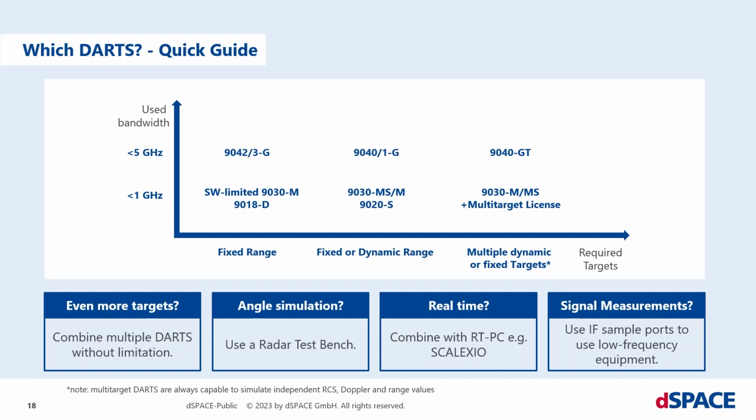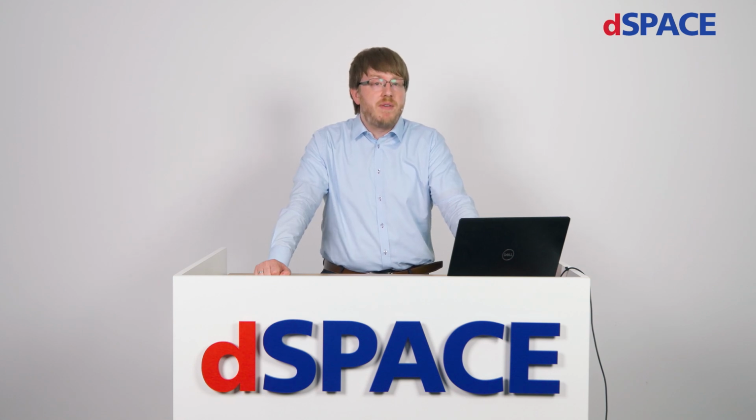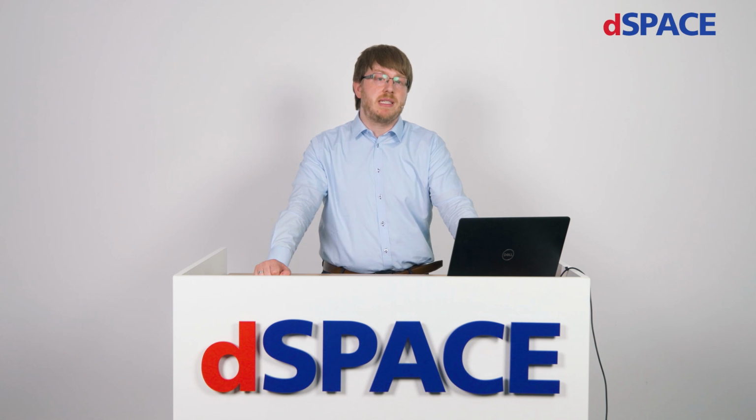As you saw before, these systems are very powerful and can be modularly expanded to include more radars, other sensors, or generally components that should be covered by a test. And the last question is, do we want to do some additional measurements, such as the emitted power of the radar sensor or the occupied bandwidth? In that case, we can use the IF sample ports on the DARTS to attach measurement equipment that works in the single-digit gigahertz range instead of expensive radio frequency equipment. And if all of this is done, you have configured the optimal system for your test requirements.